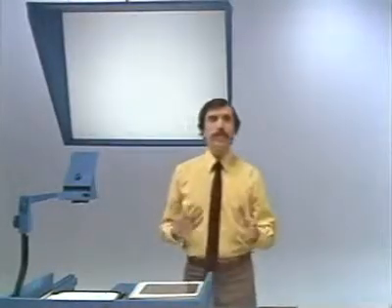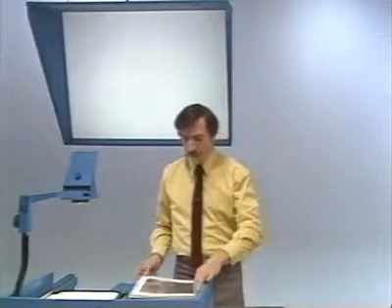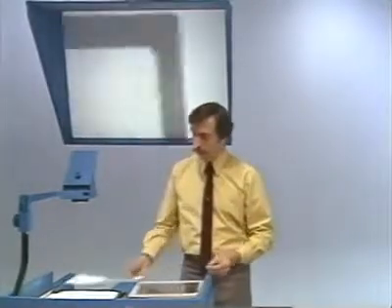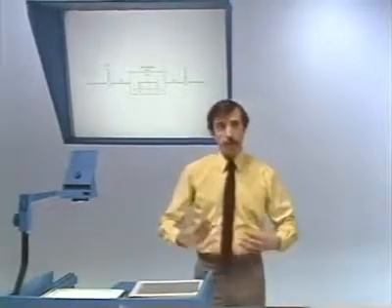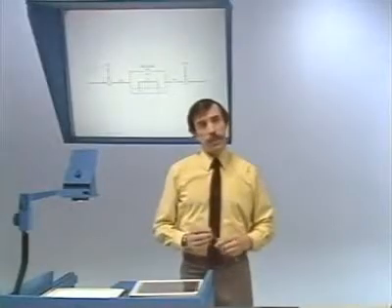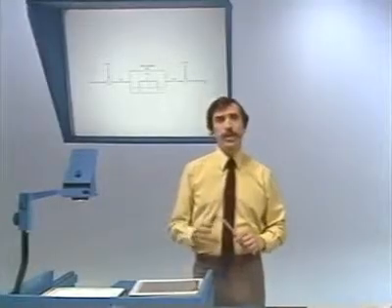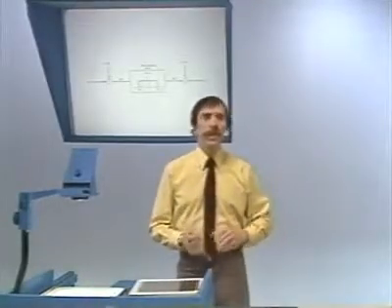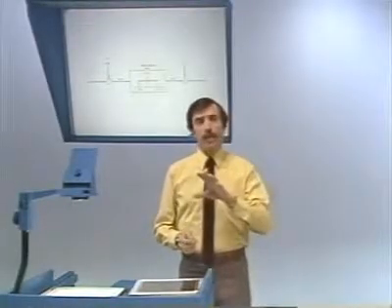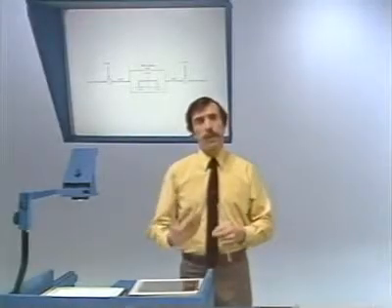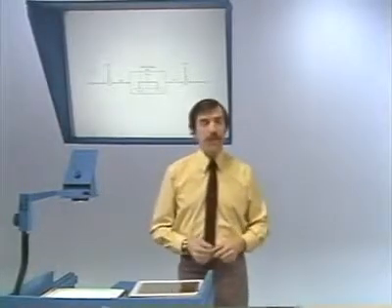Okay, now there are lots of applications of amplitude modulation, and we'll be seeing a number of these as we go through the discussion. What I'd like to do is just indicate briefly one now, which is an application that, in fact, surfaces fairly often in the context of a complex exponential carrier. And that is the notion of using modulation to permit the application of a very well-designed and implemented low-pass filter to be used as a bandpass filter and, in fact, as a set of bandpass filters.